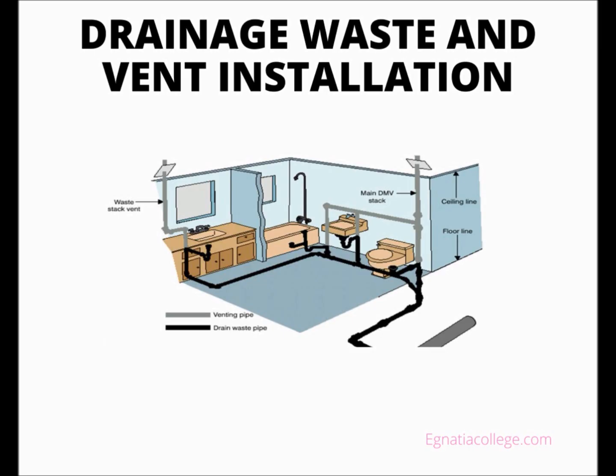Some job sites require the piping system to begin at the building drain exit location. Other conditions dictate that the piping must be installed so that the last connection of the building drain is made with the building sewer. Many plumbers install the piping on the floors above and stub all vertical drains into a basement or crawl space. Then they install the building drain.